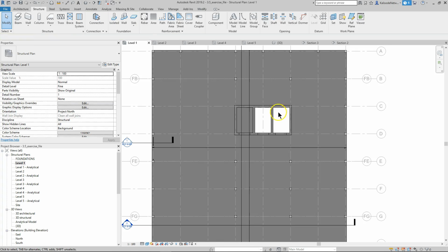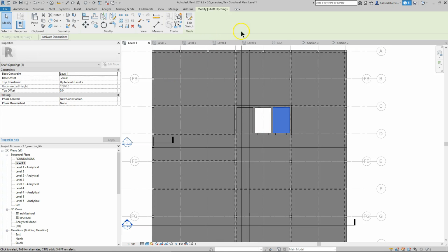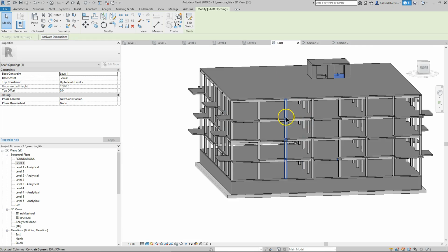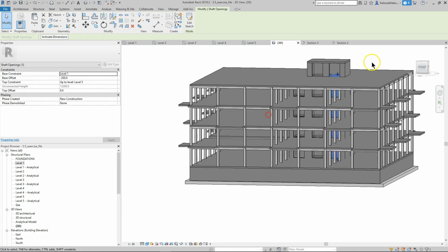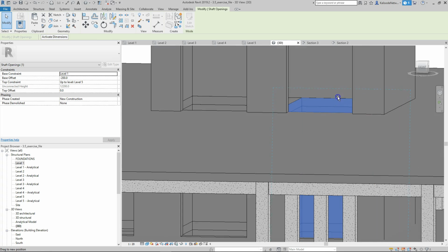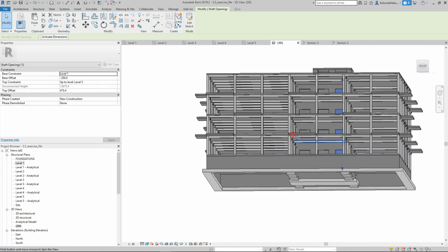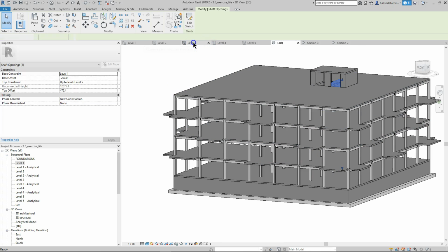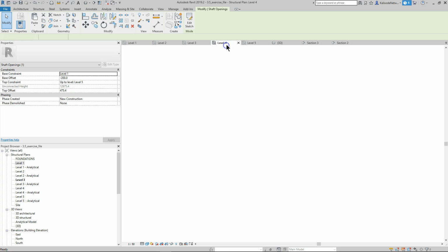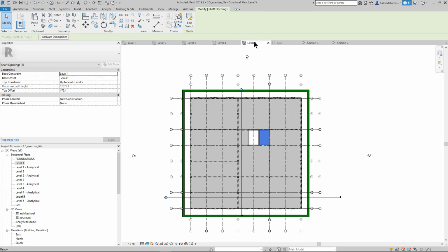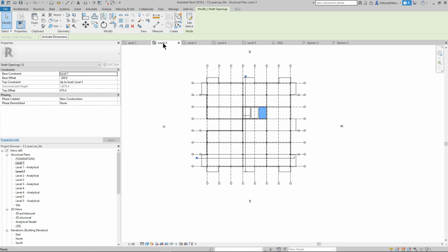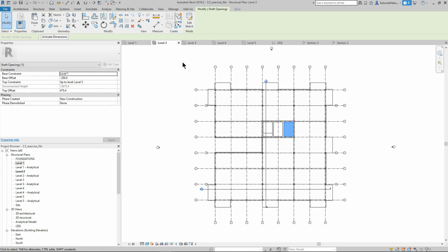And this is a modifier. It's a negative volume which is subtracting. You can see it here. See this blue volume? I can even extend it in height. This is a subtractor, a modifier which is subtracting material from the slab, so this elevator shaft is continuous now, and it's saving a lot of time. Instead of piercing and cutting every slab, I just do that with a modifier.